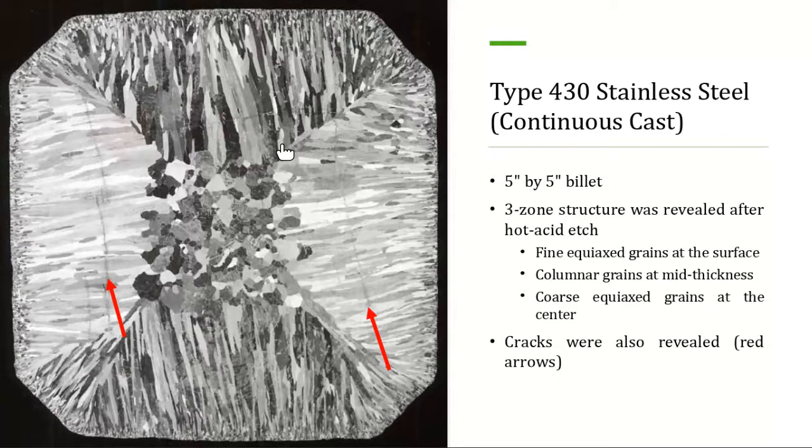Chances are this is going to go through a different type of process after the billet has been formed. Typically, it'll go through a hot rolling process. So once again, under higher temperatures, it gets hot formed. So those cracks will actually mend themselves and seal, and you will not have an issue unless those cracks were filled with oxides and or slag from the casting process.